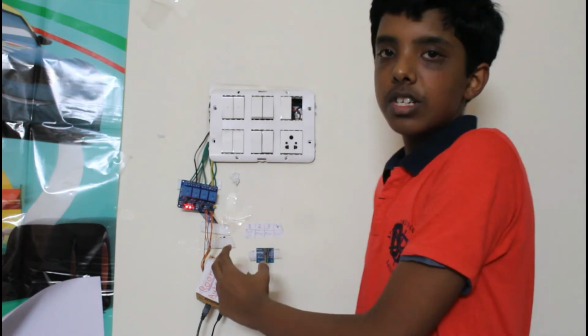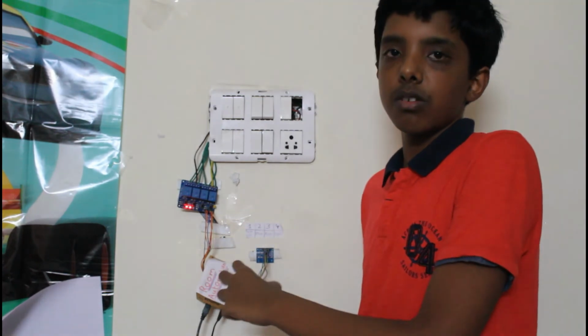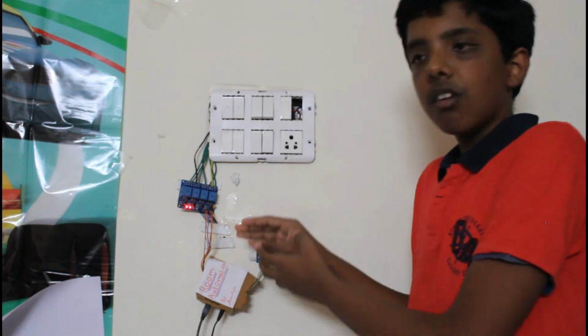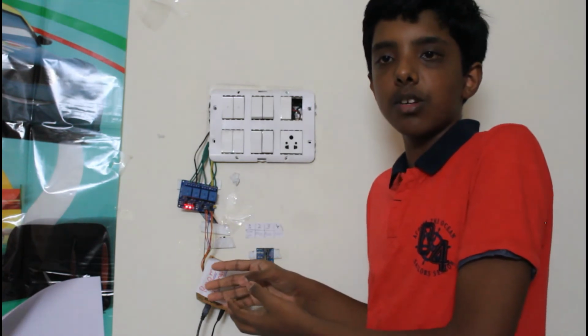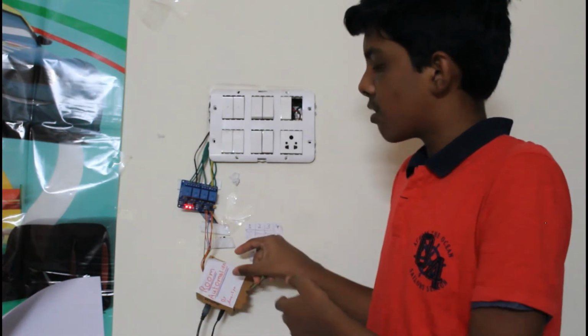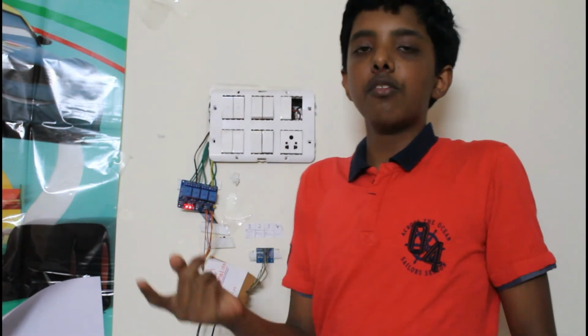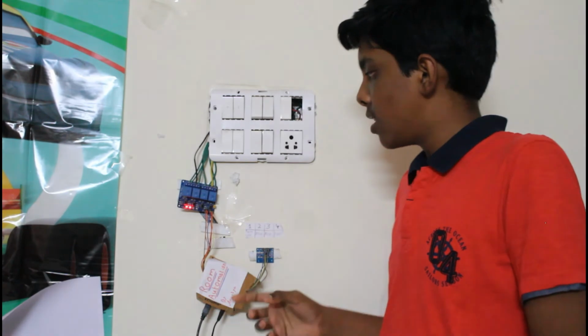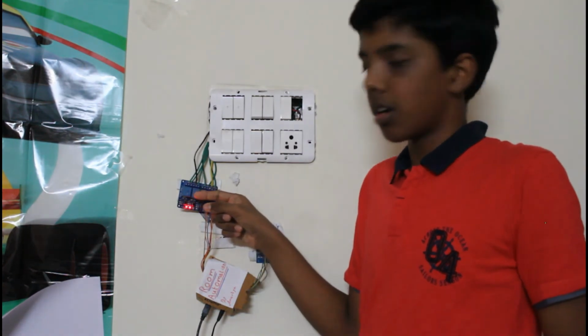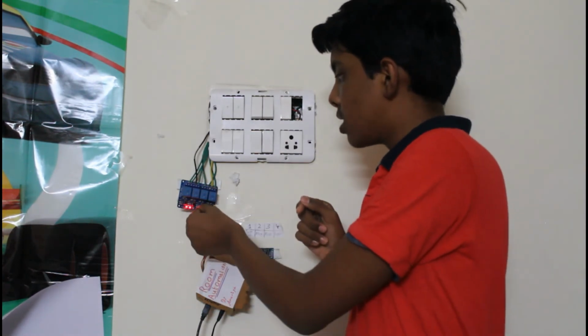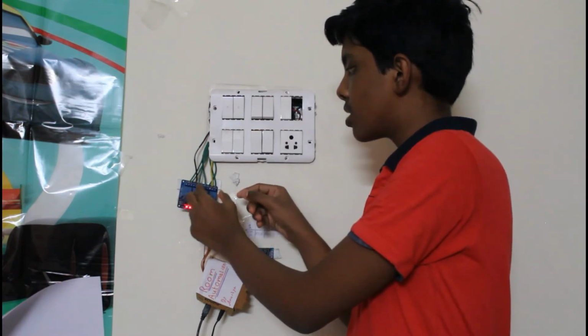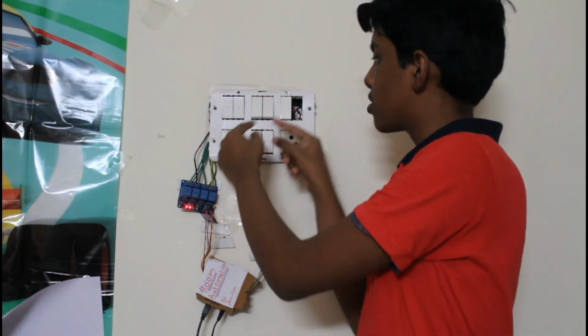So that's the code which I've written, and also to connect the Bluetooth and use the buttons, etc. Now my Arduino has the inputs. Now what should it do? The Arduino cannot control these big 270 volt or 250 volt appliances by itself. So that's why it's using the help of this relay board. It gives a 5 volt signal to the relays, which are connected to this main board.